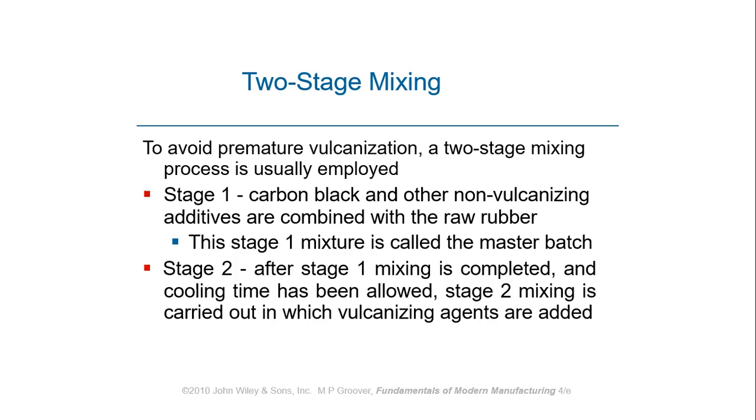cooling time is allowed. Then the second mixing is carried out in which the vulcanizing agents are added. At first, in the first stage, the additives are added, and then in the second stage, the vulcanizing agents are added into the rubber, and then the second stage mixing is carried out to conduct the vulcanization.